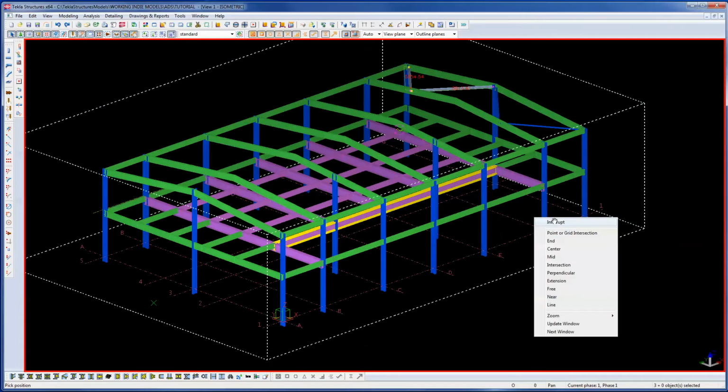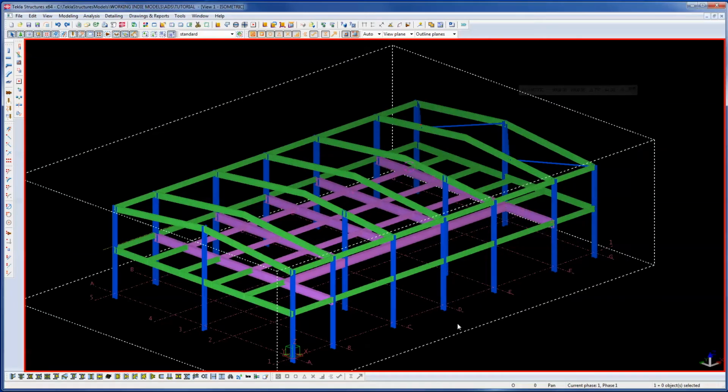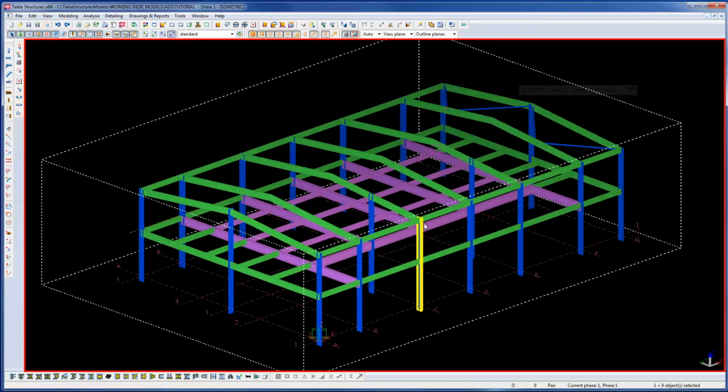The next stage will be to produce general arrangement drawings, floor plans, foundation plan, sections, etc. for checking that the sections that you've got in are correct, and that everything is dimensioned correctly. There's no point going in, connecting all this up and then finding out that half your sections are wrong, and that you've got your eaves or your ridge at the wrong place, etc, etc.